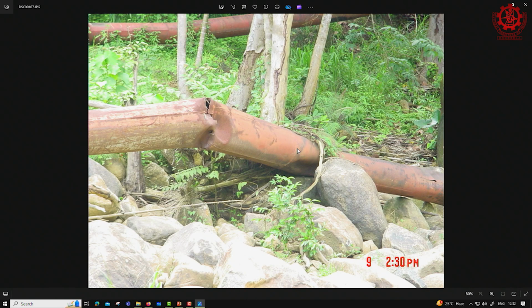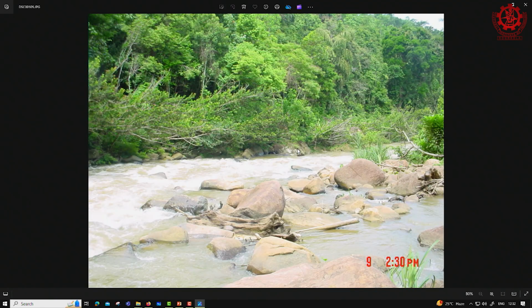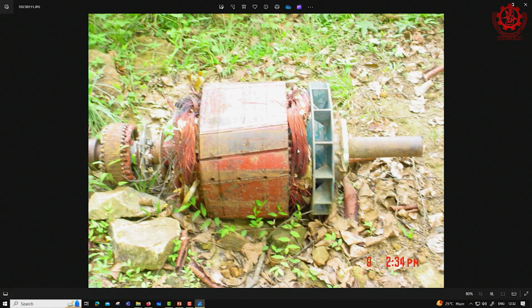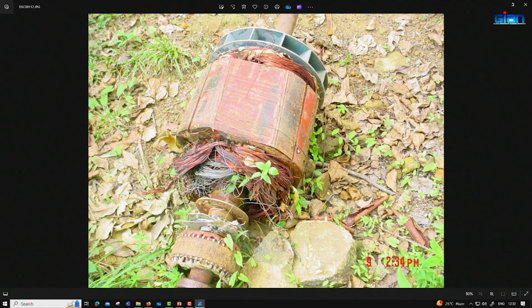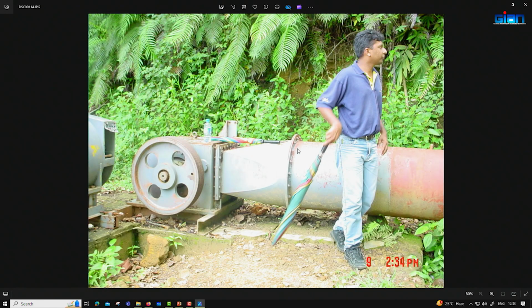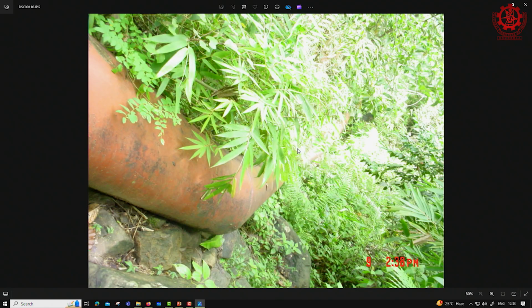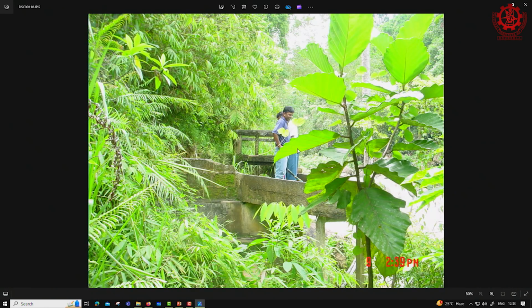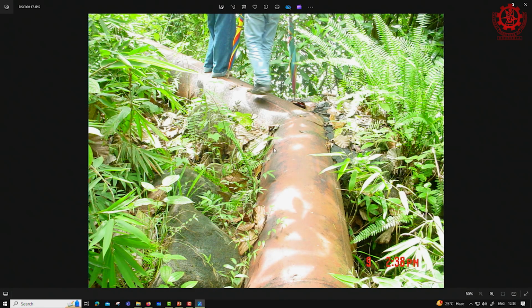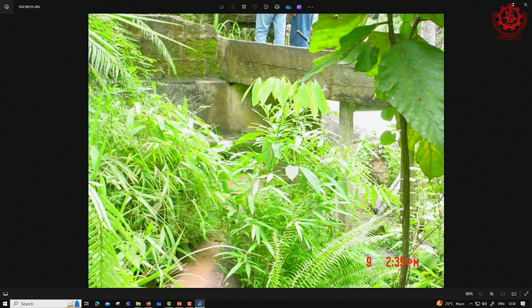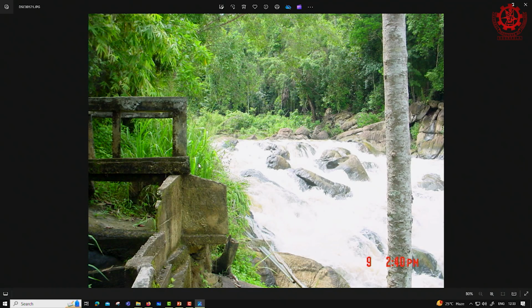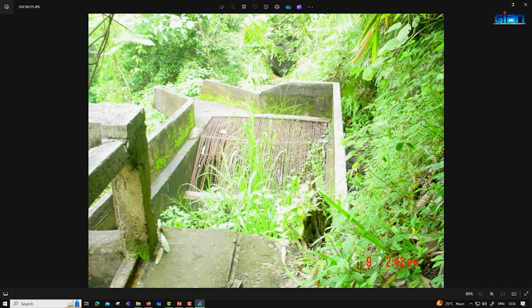See, the whole plant had been abandoned. They are my engineers who went with me. You can see they have not done proper anchors, right. At bends they have not done proper anchors, just put some concrete and tried to hold it. That will not work, right. So, they have learnt a hard lesson. See, it is a trash rack, all destroyed.